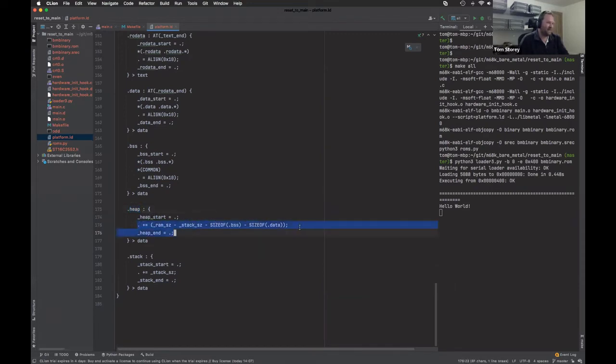You can see it all here in these formulas and equations. One thing you wouldn't want to happen is to do a bunch of memory allocations, and then all of a sudden you start allocating memory from what your supervisor stack is trying to work with. You wouldn't really want that. That might cause you some headaches. So it obviously doesn't guarantee that something can't allocate memory from that little slice taken away from the stack, but it's one little thing that you can do, I suppose.